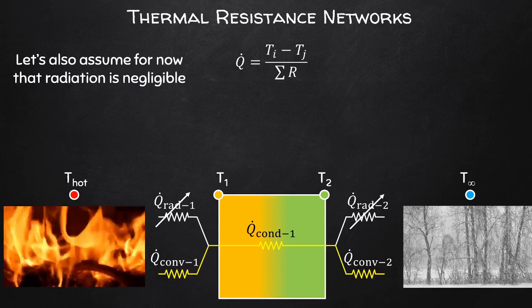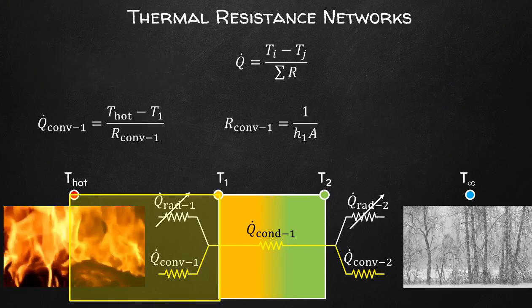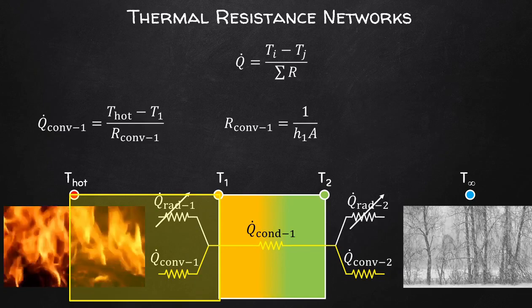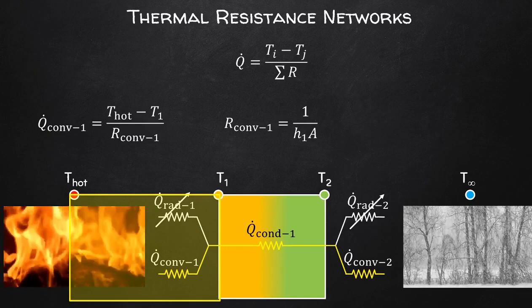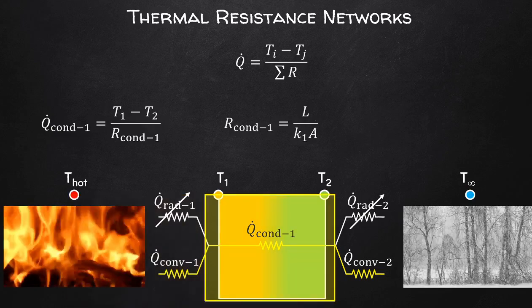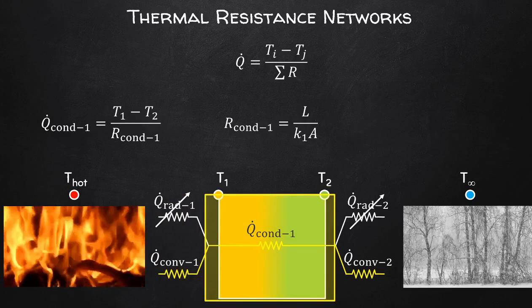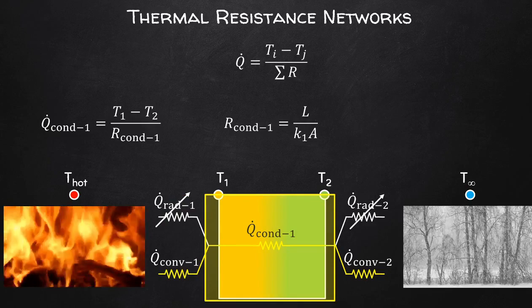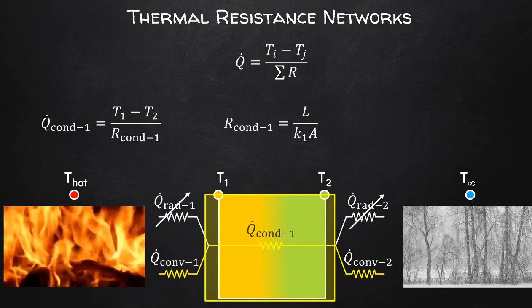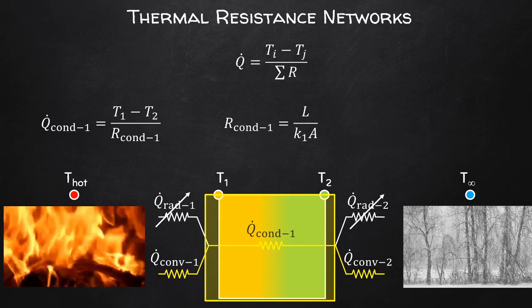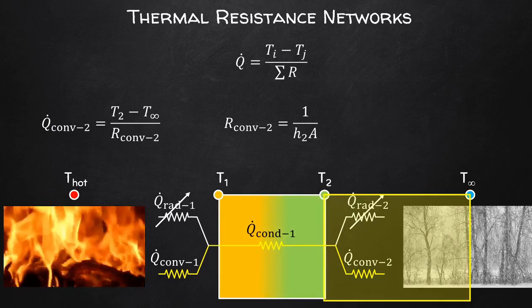Right, so to the left of our diagram, we have resistance due to the limitations of convective heat transfer to transfer energy. And in the middle, we have the thermal conductivity, the length, and the area through which heat must flow, which provides additional resistance to conduct heat through the body or through the substance.